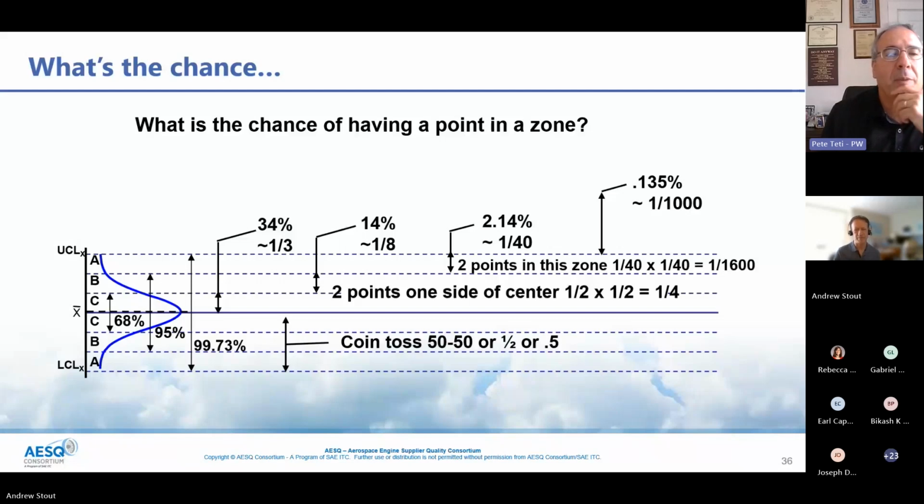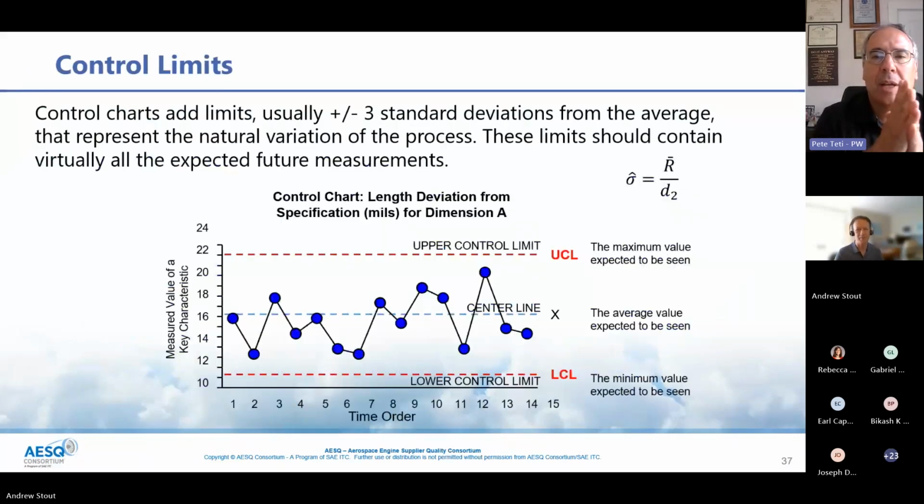And 50% of all values would be expected on either side of the bell, and that's due to its symmetry property. Well, look here, a third of all values are expected to be within plus 1 sigma or minus 1 sigma from that mean, and so forth. Again, I won't read all these off. You can look at this, but you can see how many points are expected to fall outside the control limit? About 3 out of 1,000. That's a pretty rare event.